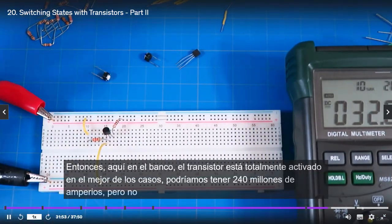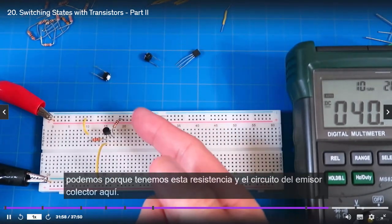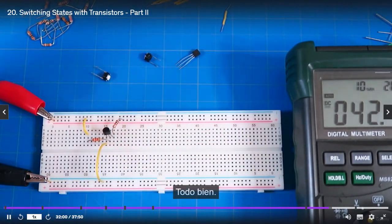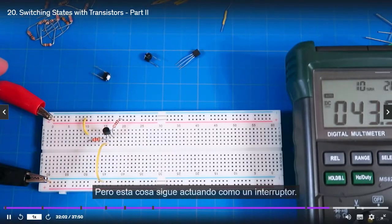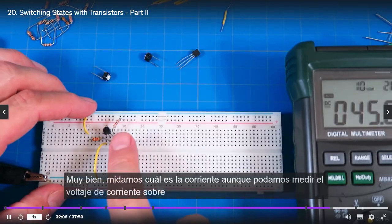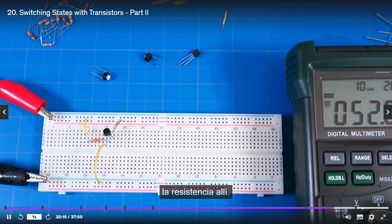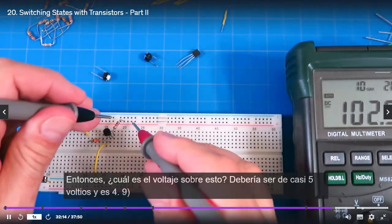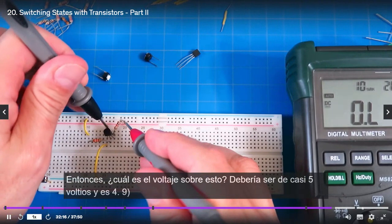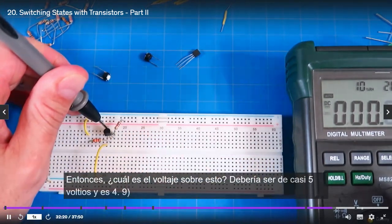At best, we could have got 240 milliamps, but we can't because we've got this resistor in the collector emitter circuit here, all right? But this thing is still acting as a switch, all right? Let's measure what the current is. Even though we can measure the current, we'll measure the voltage over the resistor there, right, to compute the current. So again, let's do that. So what's the voltage over this? And it should be almost 5 volts, and it is. It's 4.9. There you go.